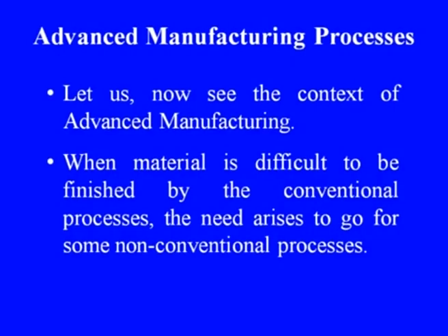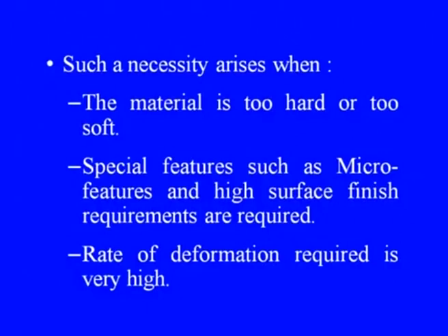Let us now see the context of advanced manufacturing. When material is difficult to be finished by the conventional processes, the need arises to go for some non-conventional processes. Such a necessity arises when the material is too hard or too soft. Special features such as micro features and high surface finish requirements are required. Rate of deformation required is very high.